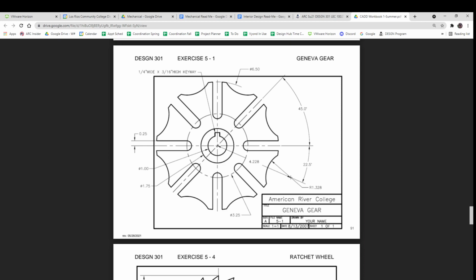Yeah. Well, so it depends. When you're doing power transmission, it depends on how much power there is. If you do power transmission, you want what's called a spline, and there's almost like gear teeth instead of just a keyway.